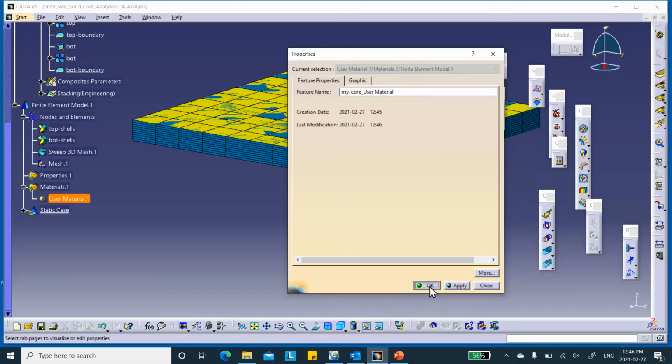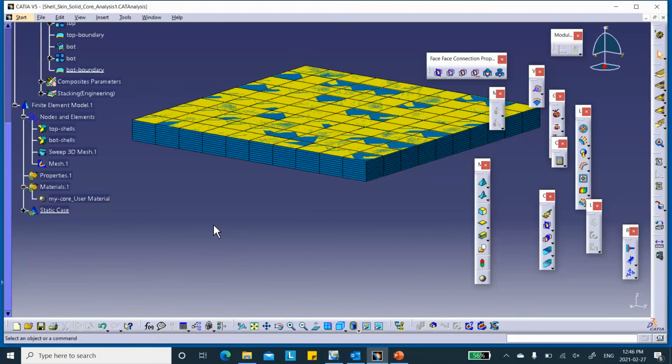Okay, fine. Good. Now, also, there are no 3D properties associated with these solid elements. That's because I just created the elements, but not their properties. So what you do now is you go over here under this, see that? These are the properties: 1D property, 2D property, composite property, and I-beam.